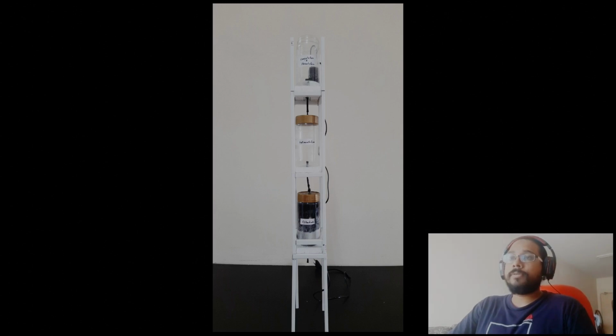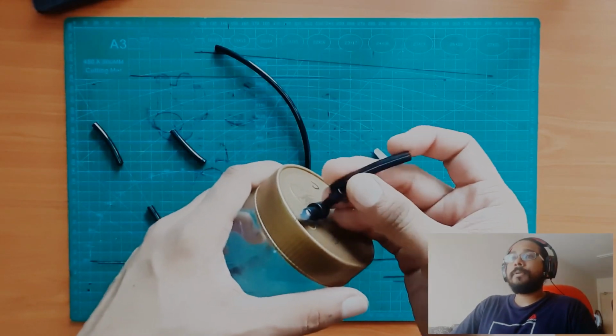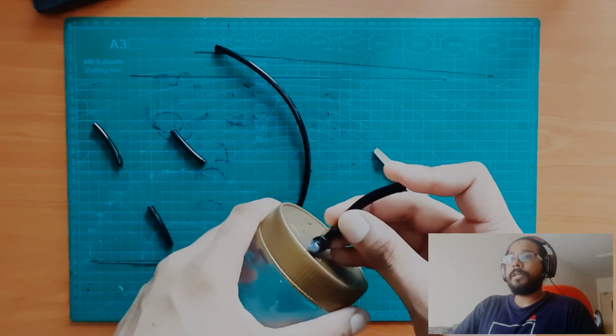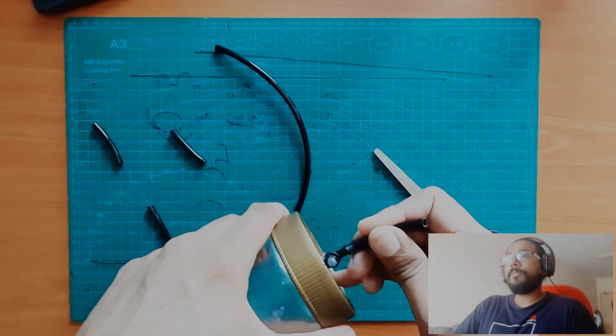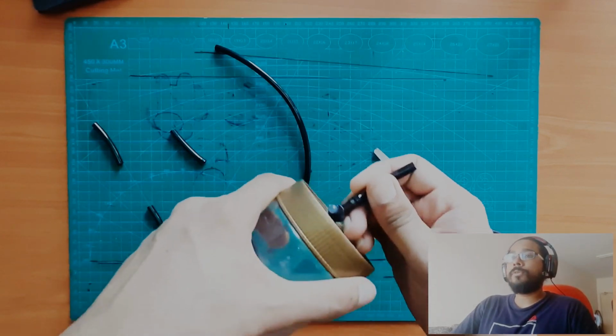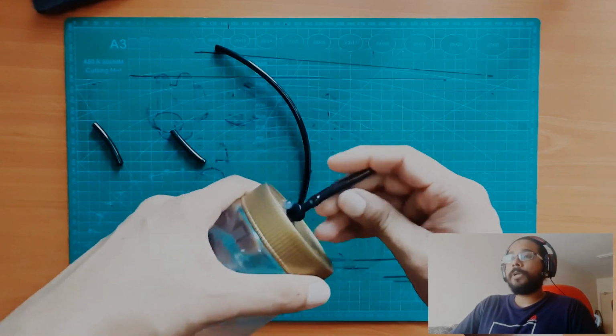It will have a charcoal, sand, and stone filter, and the device will use gravitational flow to pass water from one level to another. To make the device, step number 1 is to prepare the jar for flow of water by drilling a hole on top and putting a PET with hot glue so that PE tubing can be connected to it.